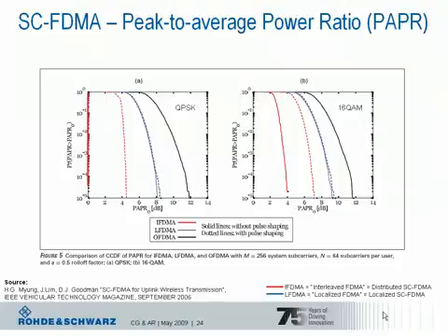This chart shows the complementary cumulative distribution function, which describes the probability distribution of the peak-to-average power ratio. The CCDF is displayed for OFDMA, so for the downlink, and for both modes of single-carrier FDMA, localized and interleaved FDMA. This data is taken from an article published in IEEE magazine back in September 2006, so in the very early days of LTE definition.